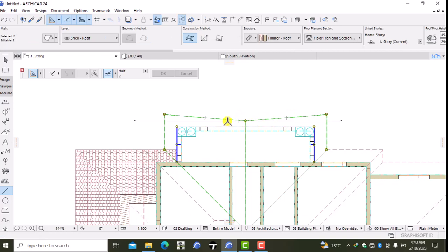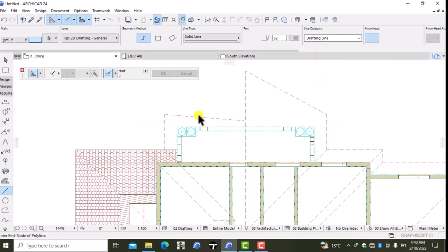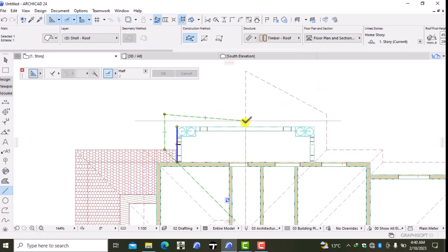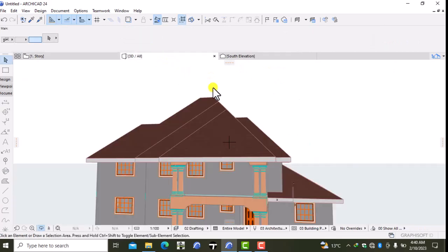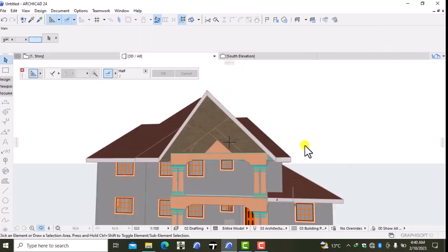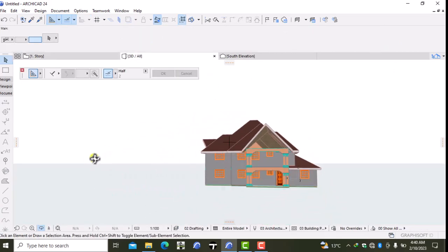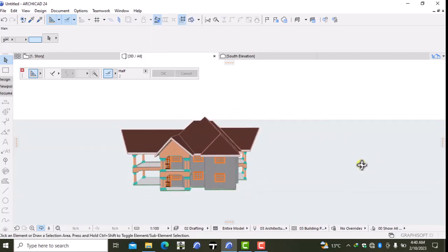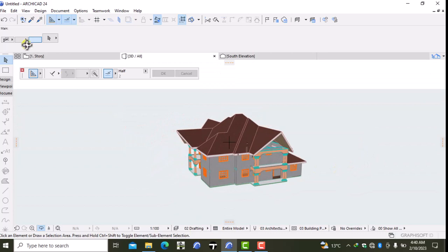Practically just drag this at a distance of 2400. This other point, and select this other node and just drag it to this point. Something like that. And I can go to 3D. After that, on that side, I just need to do a wall on this again. The same wall that we had on that at the end.